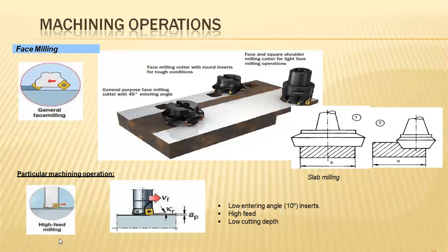During the high feed milling, it is particularly utilized for machining operations where conditioning is processed with respect to a low entering angle of 10 degrees of inserts, high feeding, and low cutting depth.